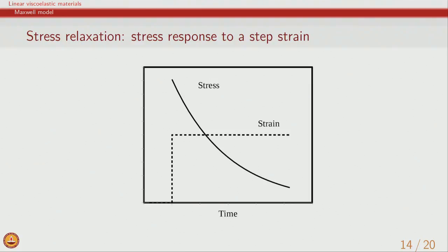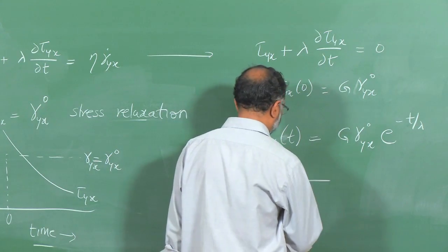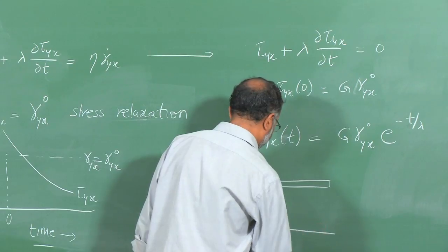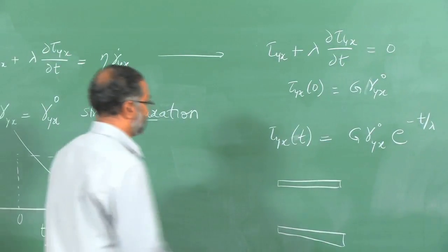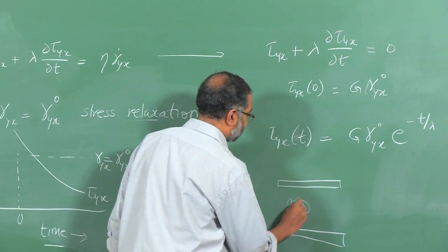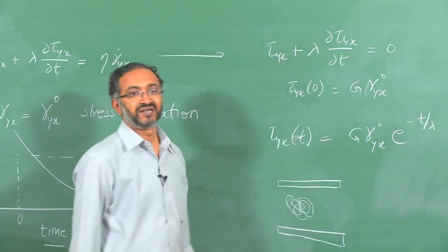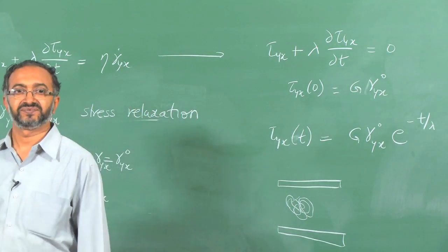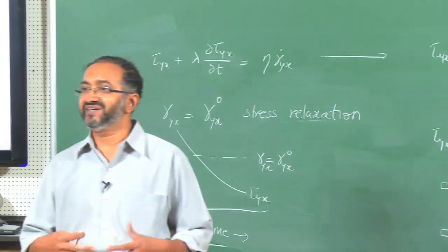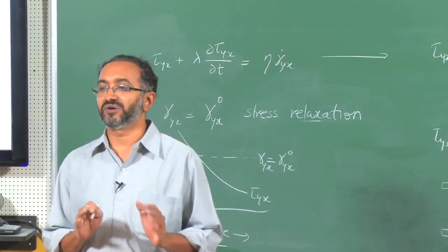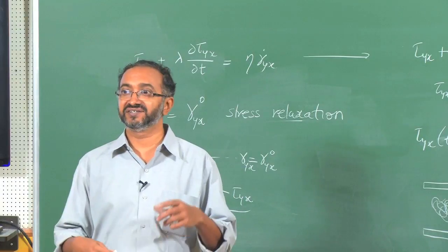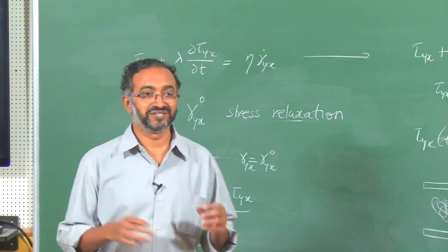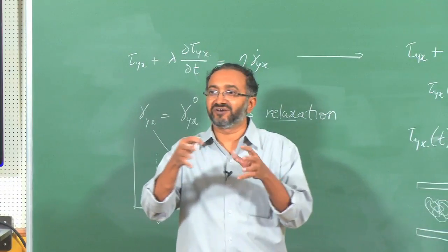And we can think of this in terms of a macromolecule, right, because it is always helpful for us to think in terms of microstructure and molecular mechanisms. That is one of the important things for rheology. So, let us say we have a solution of polymer molecules and now we are applying a strain on it. What do we mean by stress relaxation? If it is only water molecules, then what happens is instantaneous decay, but now because we have a macromolecule which has other relaxation processes possible, which means the segments can move, the overall molecule can also move.